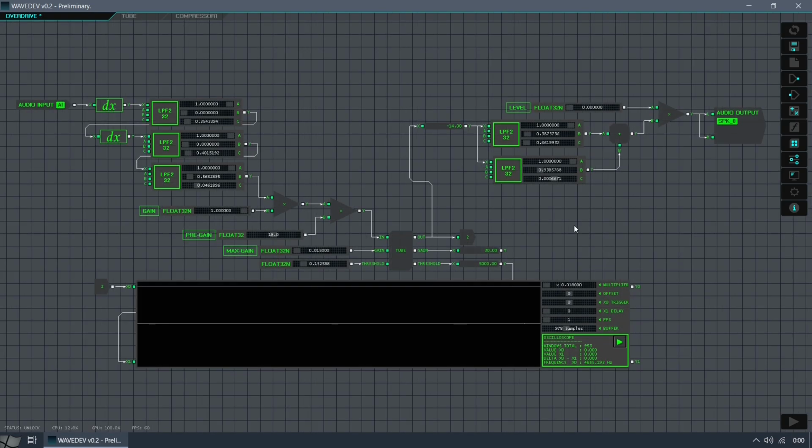In the first instance, we could work with the same distortion structure with less gain. But there is a problem that I didn't talk about before. This filtering optimizes the saturation for our effect only at higher gains. But the signal at this point is not very attractive. And when we reduce the gain, we tend to hear this signal. Remember that we have removed too much bass with these two high-pass filters. So the guitar here will feel very weak, without body.